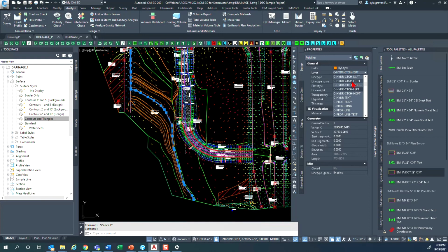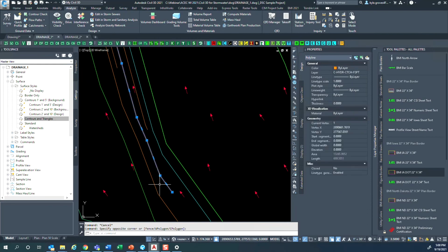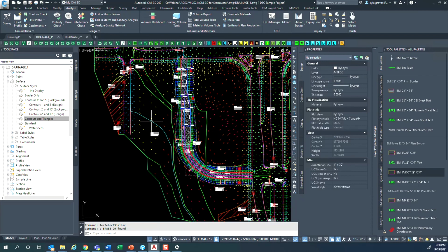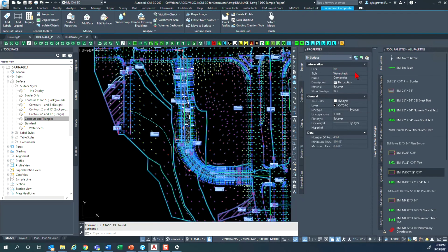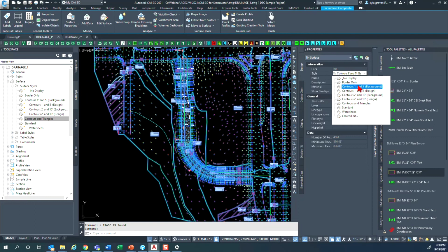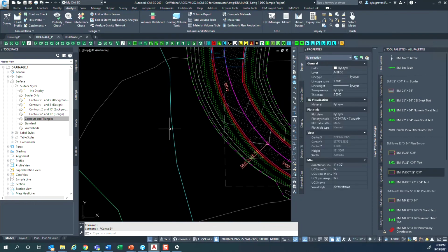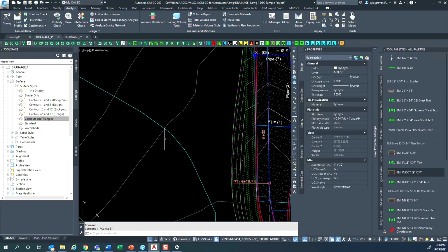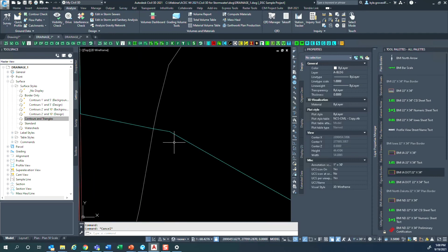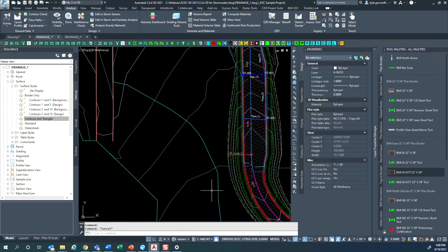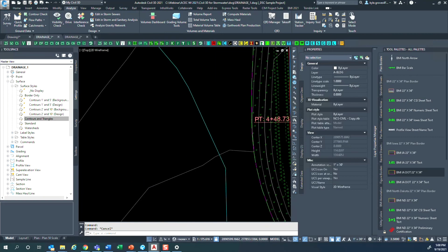So I'm going to move mine to my catchment flow path. It's going to turn cyan. Then I can simply select similar of those drafty ones, and I can delete those out. Now, again, this is the software doing its business. If I turn back on my contours, I'm still responsible, and I still would be benefited from coming through here and running my own right angle check to make sure that this water drop is always perpendicular to those contours. And in this case, it's done a pretty good job.